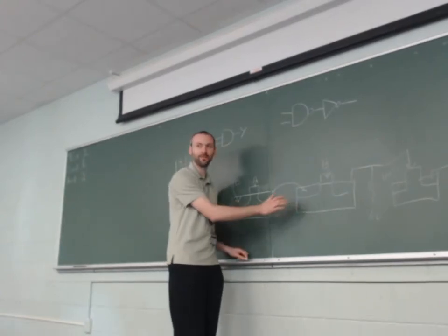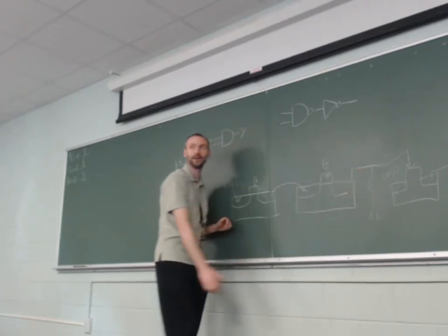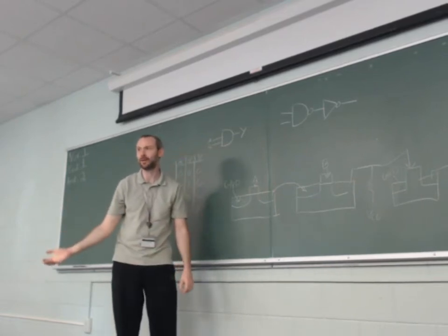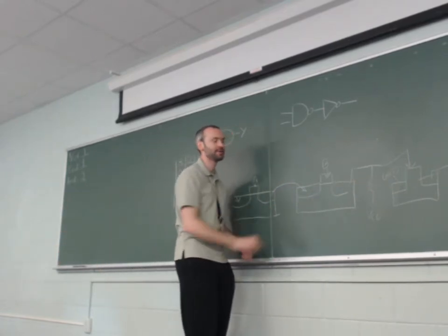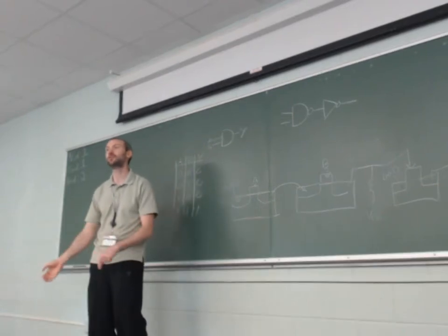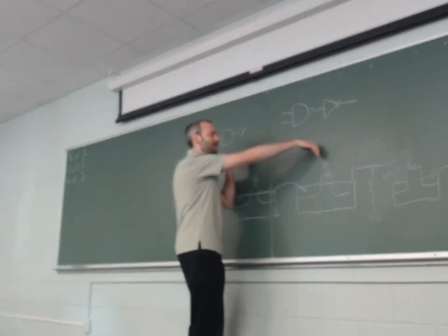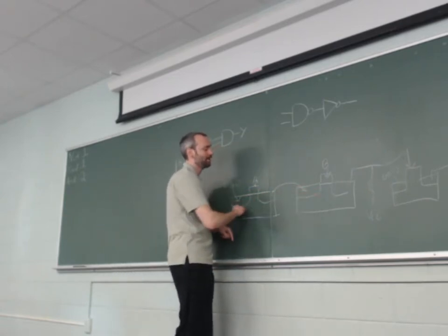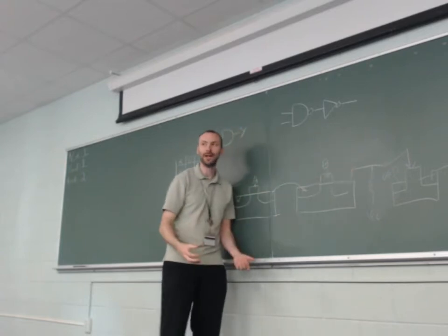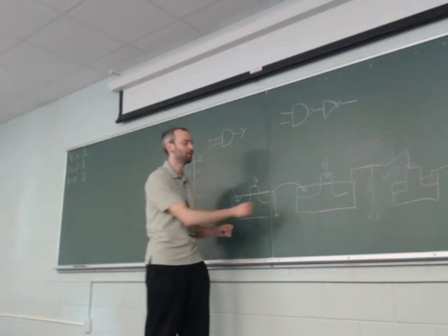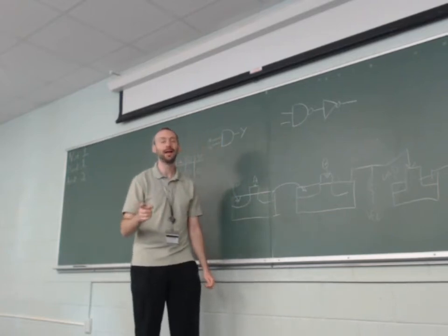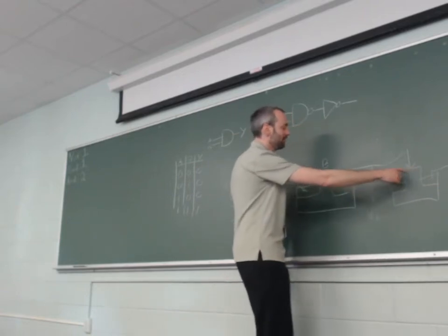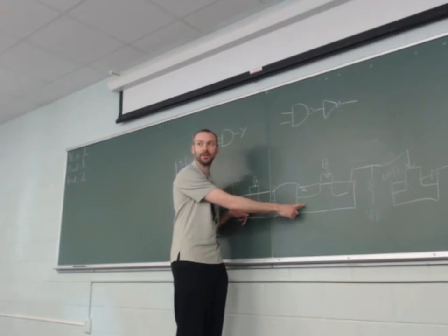Do you understand, I guess, so we'll start with the NAND. So the NAND is just this part right here, right? A and B get applied simultaneously, aka in parallel, which means that this transistor and that transistor are going to saturate to the correct value in 1 gate delay because they're both being applied at the same time. Now, in order for the inverter to saturate to the correct value, its input depends on the output of the NAND.